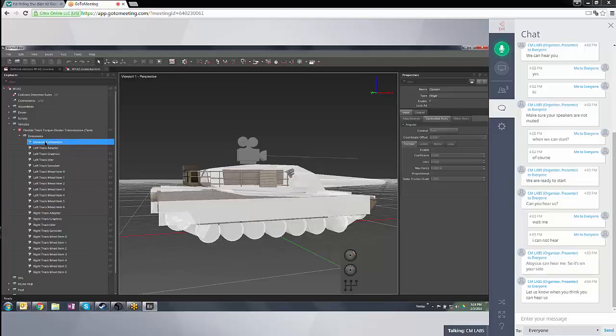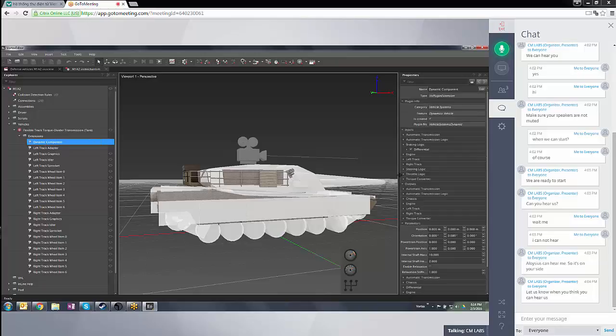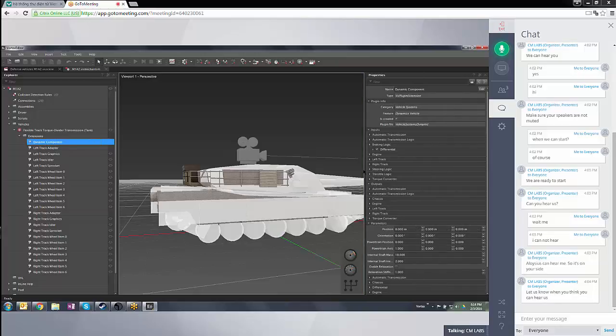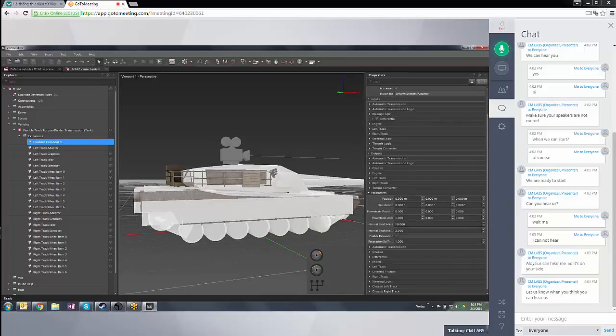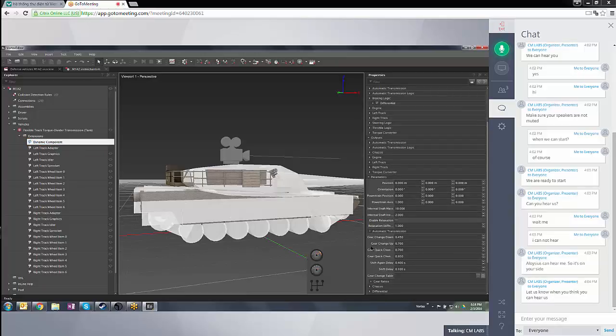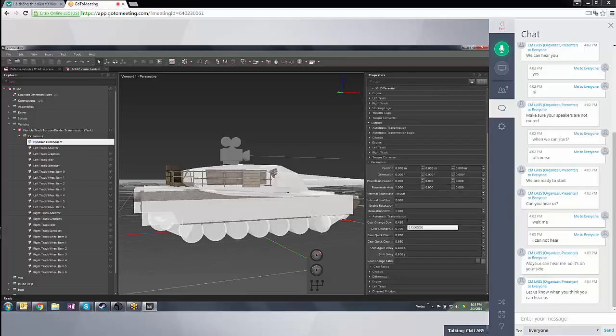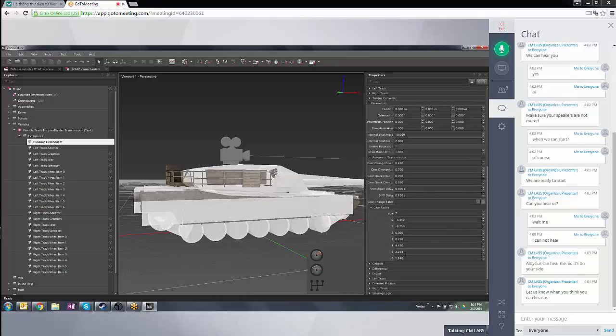Now, there are a lot of different parameters in here that are used to be able to define how the vehicle is going to behave. And that includes basic data about the position of the engine inside of the vehicle, information about the transmission. If you're simulating an automatic transmission, when will it shift gears to go up and down? Then we also have a section to be able to specify the different gear ratios. So based on the transmission, what's going to be the gear ratios for how the engine power will be scaled up or down.